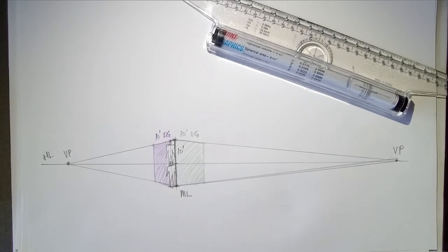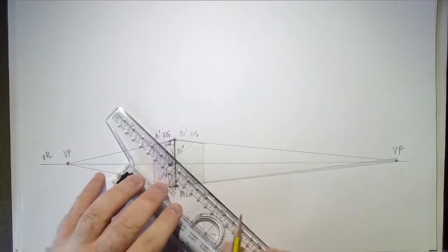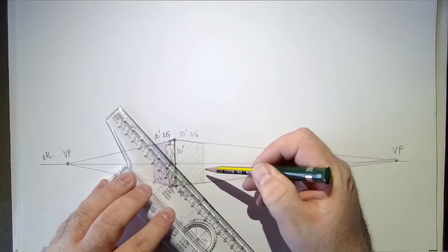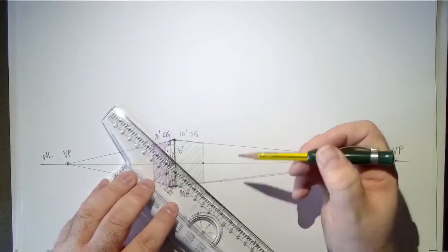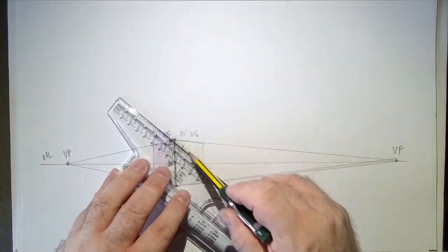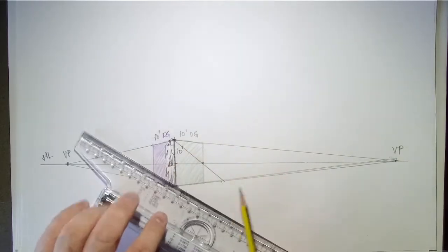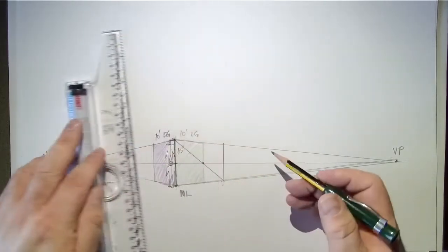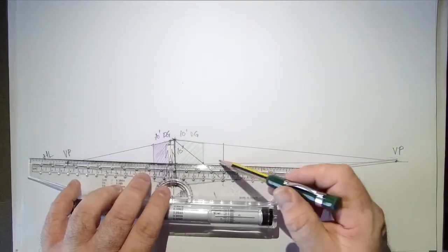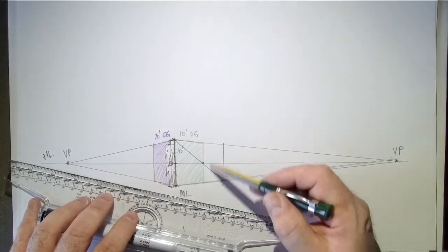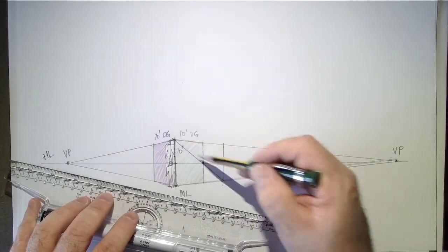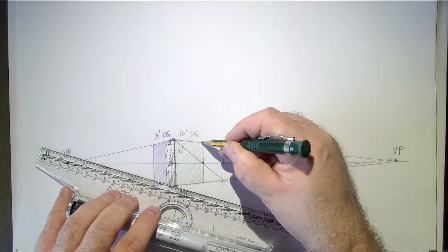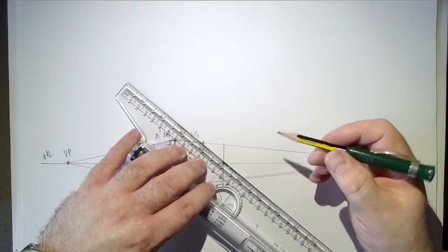Just as we did with our previous method, the way that we project the next 10 feet in space is we go from the top of this through the midpoint and then down to the base plane like so. Very similar to how we did it with 1 point perspective. So that represents the next 10 feet. If this is a 10-foot depth guess, then this represents the next 10 feet. Similar to our previous processes, we go from here through this midpoint, and that represents the next 10 feet.